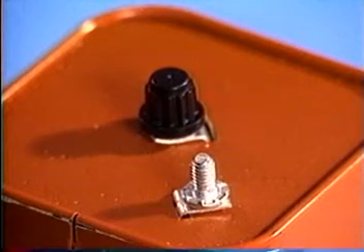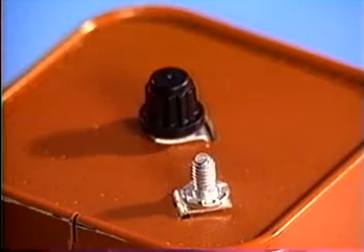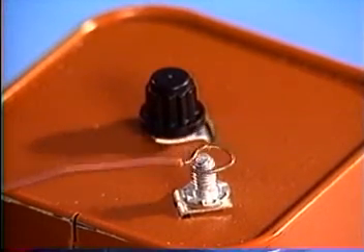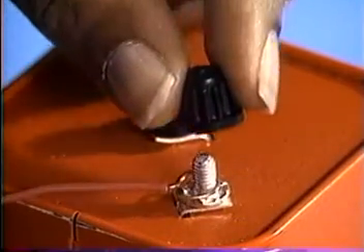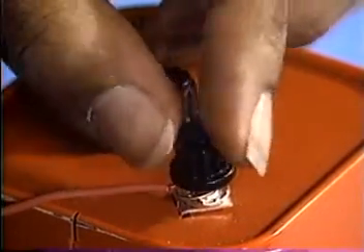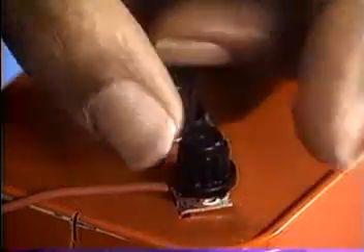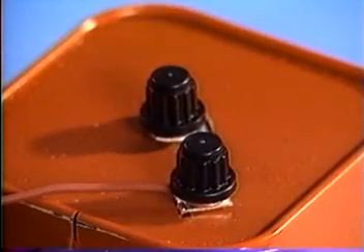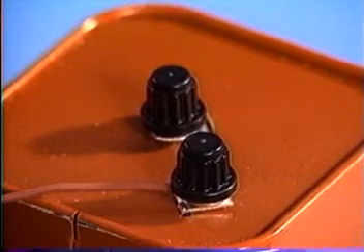Whenever you connect the wire to a terminal post, place the loop over the post so that the rotation of the nut will wrap the loop around the post. The nut or screw tightens by turning clockwise. Place the loop so it wraps in the same direction. This will help to ensure that the wire is secure.